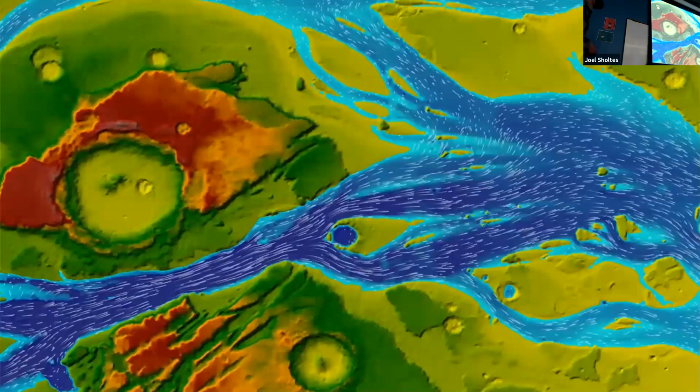Here's a picture from that Mars model that our friend did. And again, you can see flow lines. So RAS has this visualization, which will show you kind of where stream particles will go. And the faster they're moving, the longer the tails are. And it also shows you the direction. So it's just a nice way to visualize where water's moving.